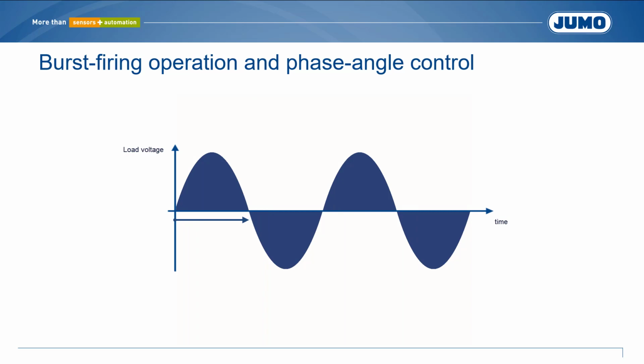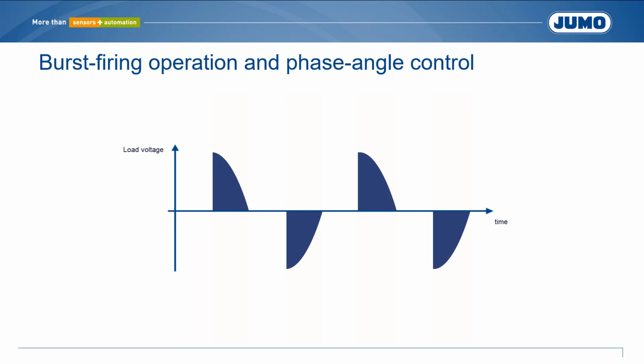The main reason for using phase angle control is a required current limitation for heating elements with very low cold resistance. The operation mode results in a high interference potential and furthermore controls reactive power. Depending on the application, mains filters and compensation systems must be used.